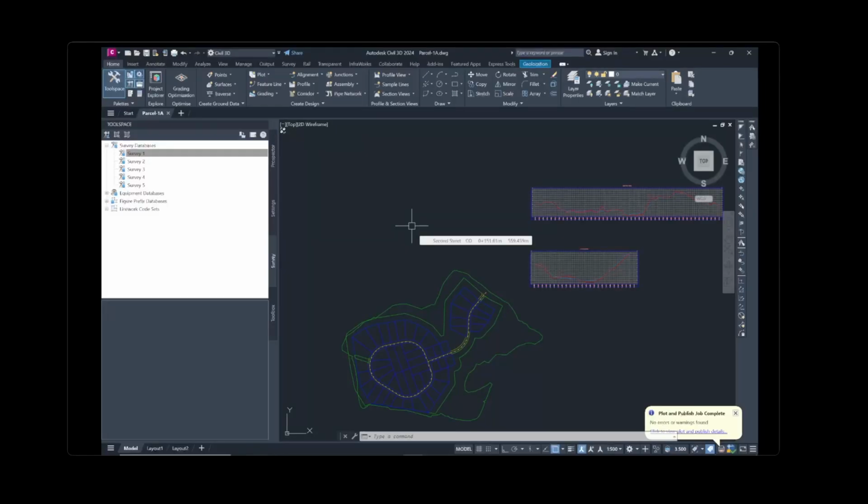We're going to go with Parcel tutorials, and this tutorial is Creating Parcels. Exercise number 1, creating parcels from AutoCAD objects. We will convert AutoCAD entities to land parcels with automatic labels that show useful topological data such as land area.